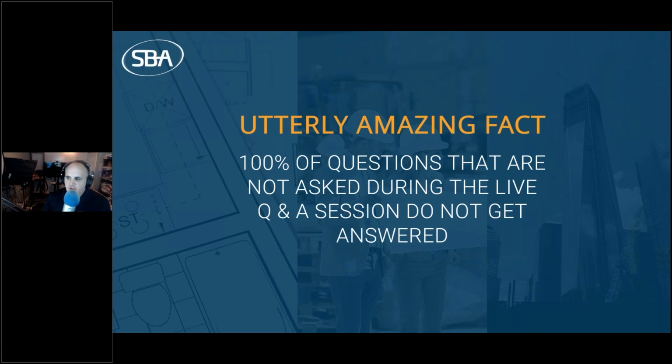Some building automation systems will support API and database consumption directly. Others will only support BACnet. So it depends on the protocols the building automation system supports, as well as the protocols and data flow types that come out of access control, lighting, AV, parking management, workforce, CMMS, the usual suspects, I would say.